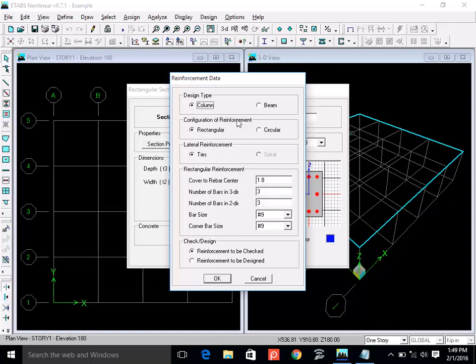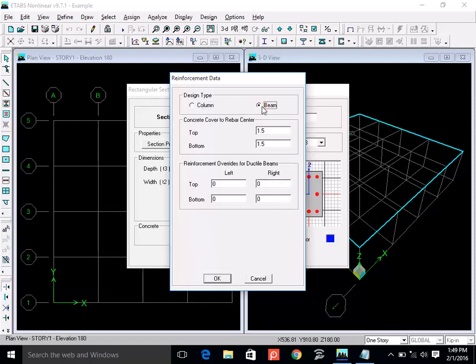Okay, so we were defining our beam and we said that it's a beam, and the cover in inches to the top bar, how much? 1.75. Okay, are you sure about this? Yes, sir. 1.75 inch. If you make the clear cover 1.5 inch, then this value will be 2.25 inch.